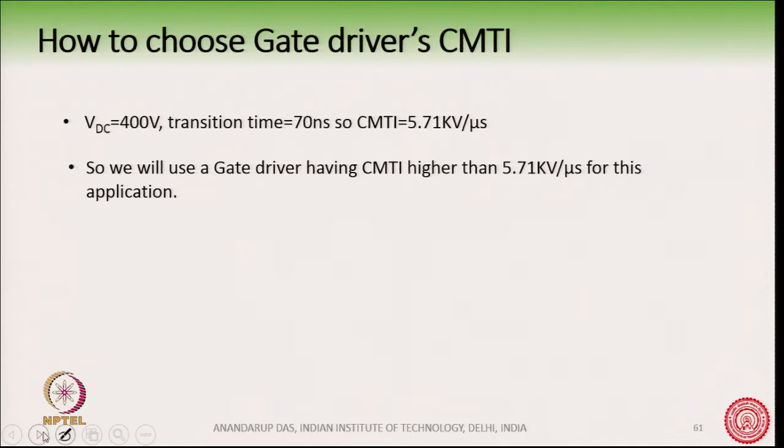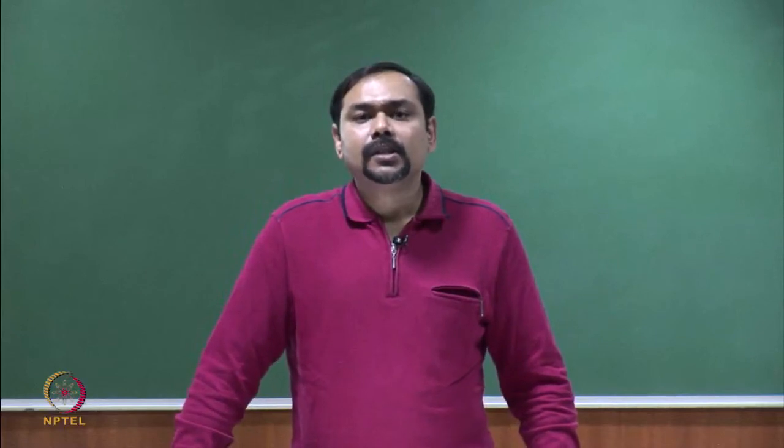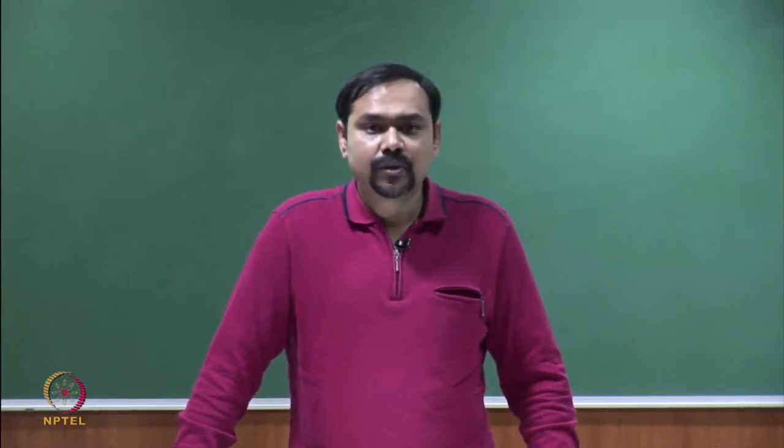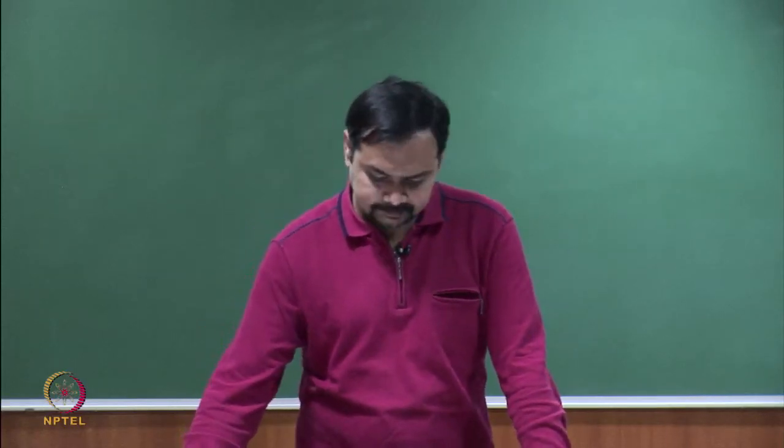So, we must use a gate driver IC having a CMTI value higher than this 5.71, and this is available in the data sheet of these gate drivers, and you should choose such a value. It is very important, this CMTI value is very important for silicon carbide or these high switching frequency devices.